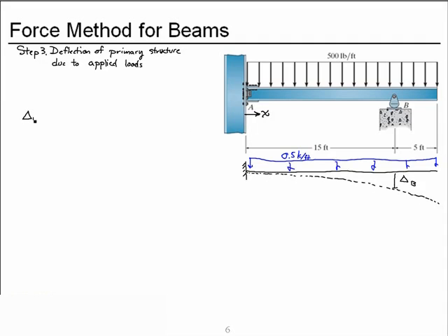we get a formula for the deflection at B of minus the distributed load, omega, over 24 EI times the distance to the point where we want to calculate displacement, that's B, raised to the fourth, minus 4 times the overall length times that x distance cubed plus 6 times the overall length squared times the distance to the point squared.